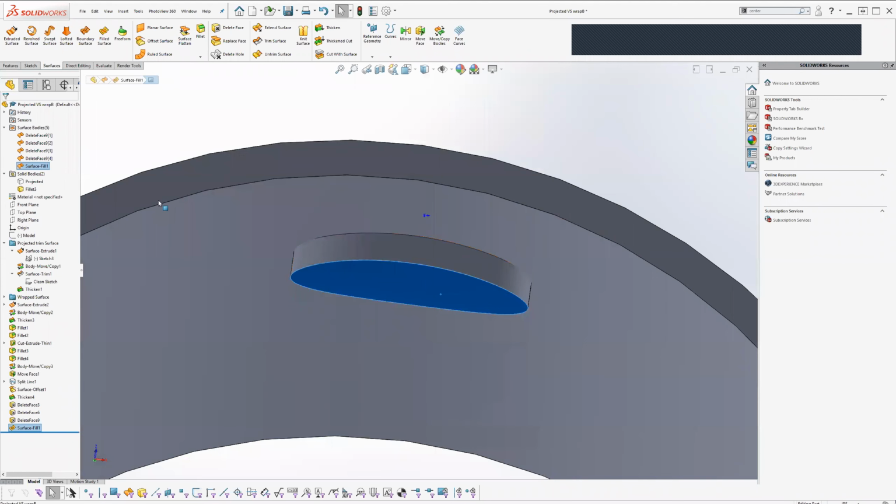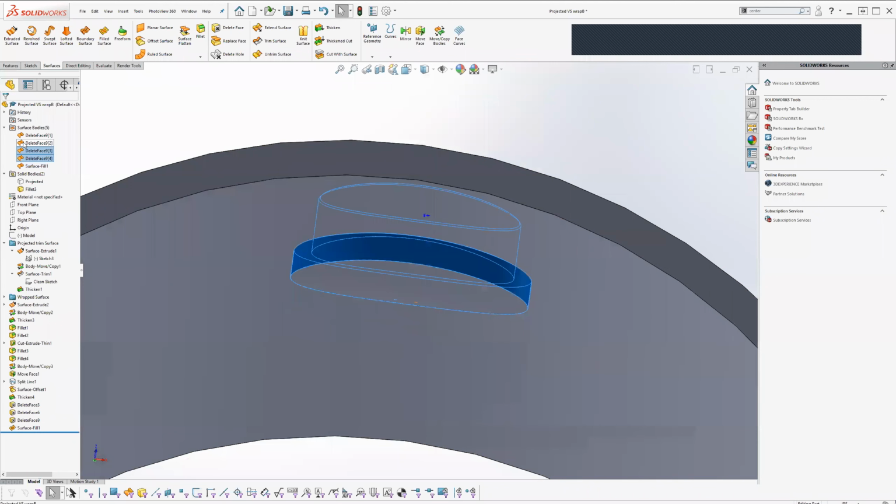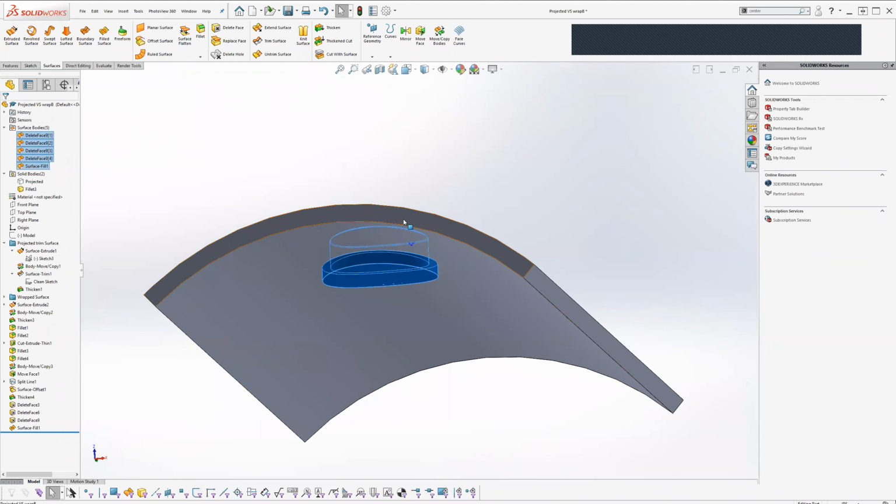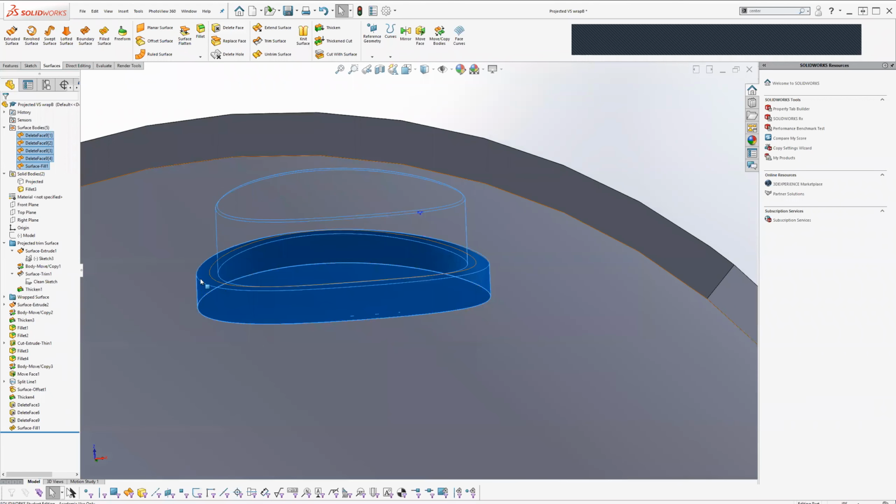Now that we have a series of faces that we're left with for all of this stuff, this entire thing becomes the button. So we kind of reconstructed this bottom piece here. Remember, there's never a dead end here in SolidWorks. There's always some way to kind of work the surfaces. Also, always work with what you have. I did that original split line because I already had a cylinder, and all I had to do was make a sketch to divide it up.